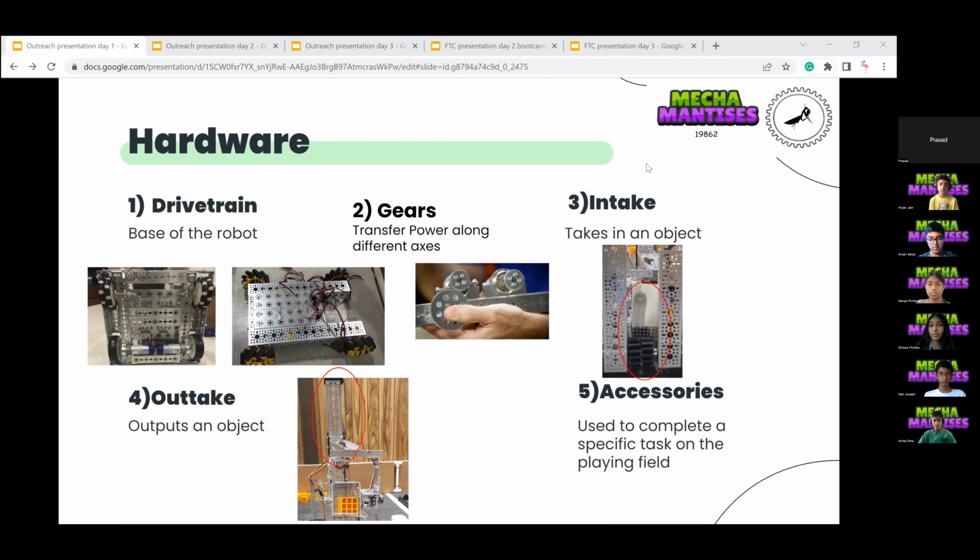Right now, we're just going to be talking about 3. The first one is traction wheels. These wheels have good grip, but they're not good at turning. The next one is omni wheels. The omni wheels can move sideways because around the edges, they have little rollers. So that's how they can move sideways, and they can also move forward.